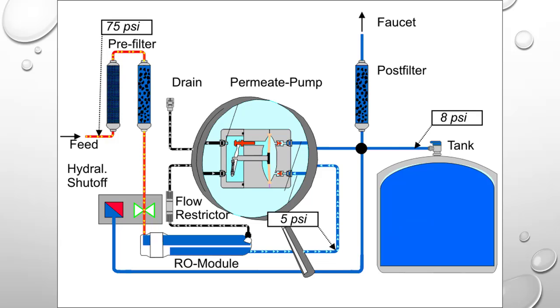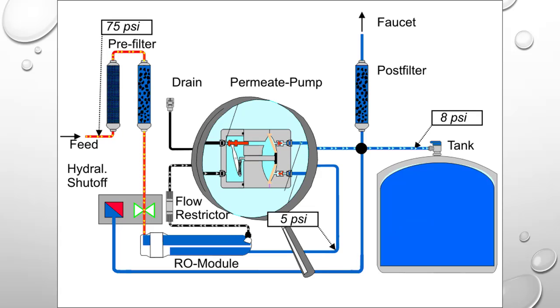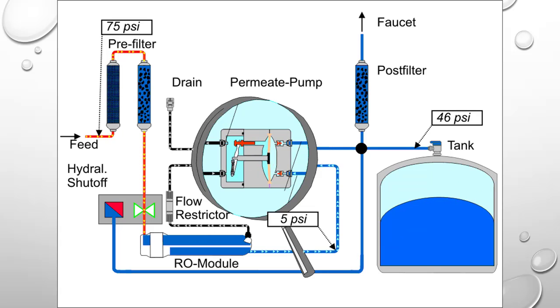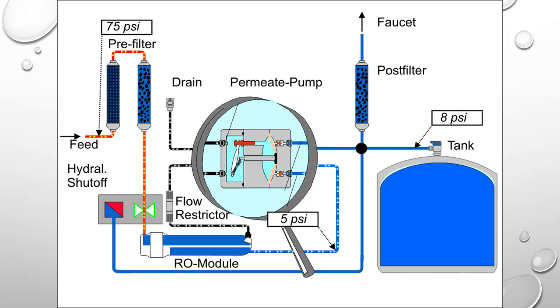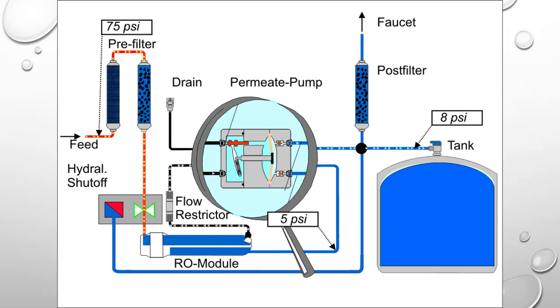So in the case of a membrane, the concentrate or wastewater coming through that membrane is really going to try and go through to the drainage line. That's why we need a flow restrictor, because that flow restrictor is going to put the brakes on that water and force it to back up in a spiral direction through that membrane to the permeate tube. But the pressure coming out of that permeate tube is extremely low.